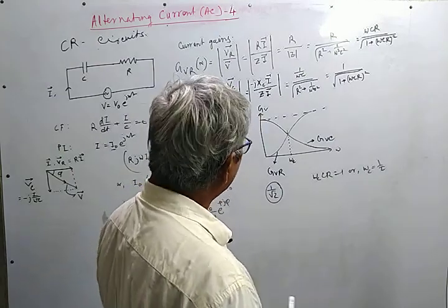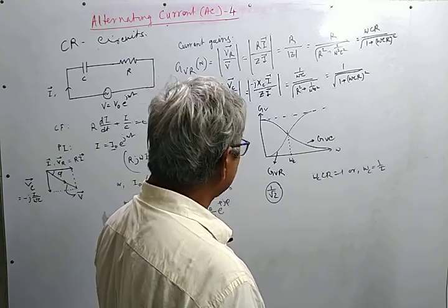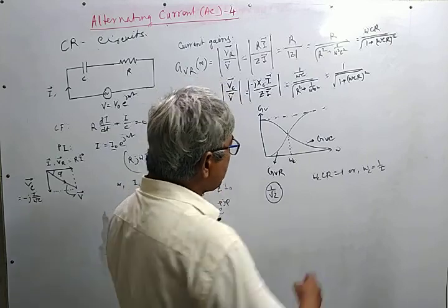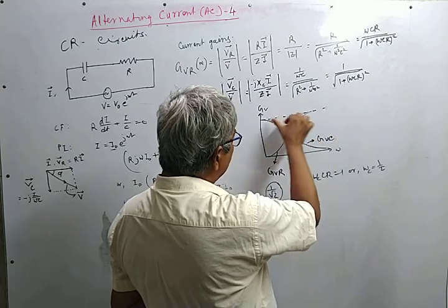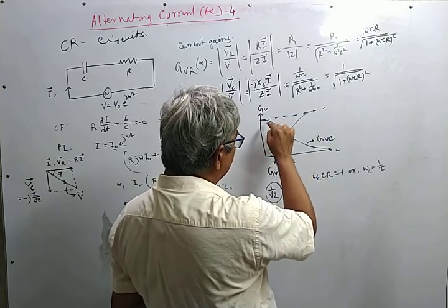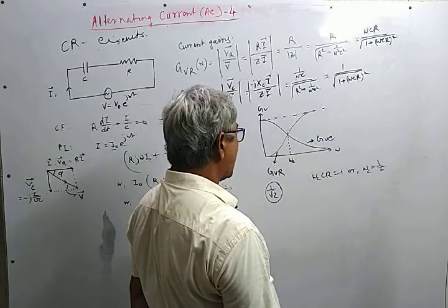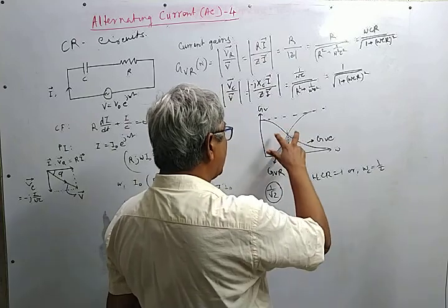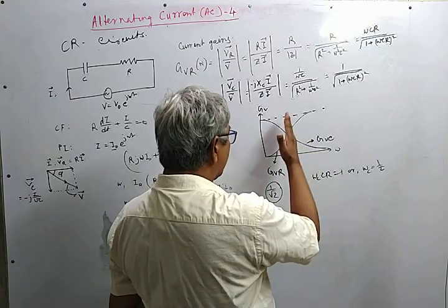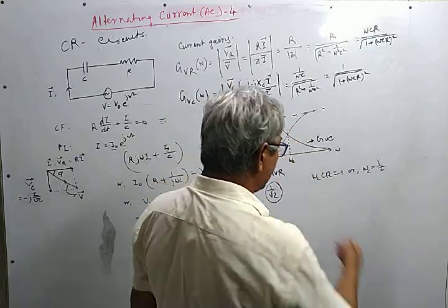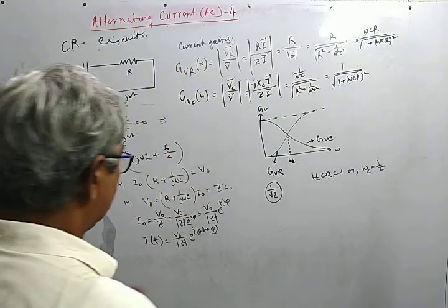and such a question has also been set in Calcutta University examination in previous years, but it is not the right way of identifying the cutoff frequency, because to know the maximum of this, one must go to the zero frequency limit, which is not practicable. So the right way is to draw both the gain curves on the same paper with the same scaling, and from the intersection point of the two gain curves one can get omega C in the right way.